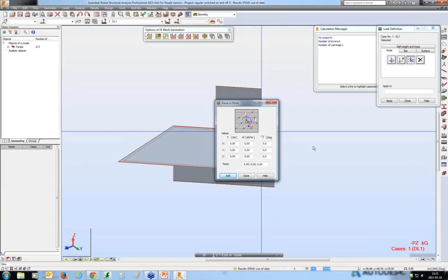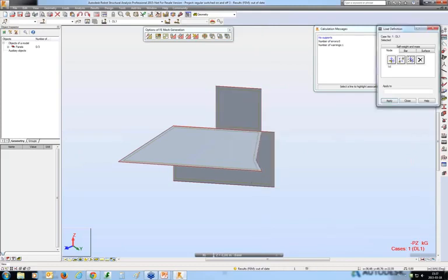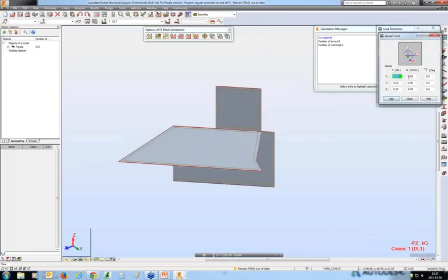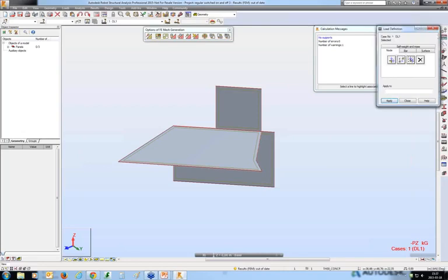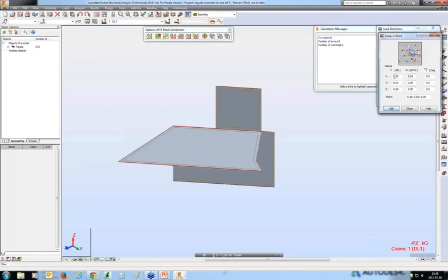So either option is available. If you define a node and apply the force in the node, then you need to remesh the panel and the mesh will adapt to the newly defined node. Otherwise, you freeze the panel and just apply the load as a force in point rather than force in a node.